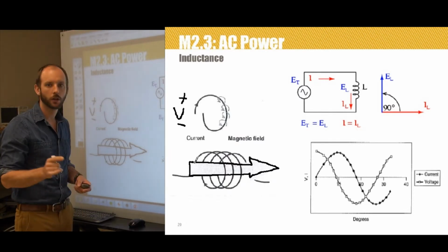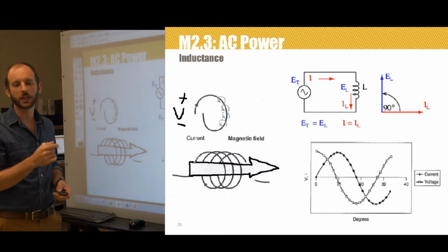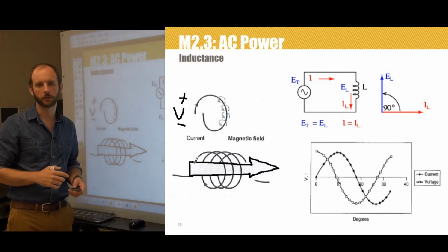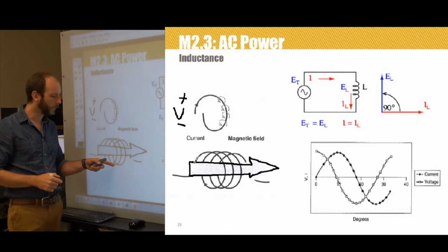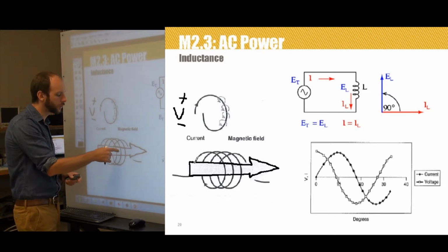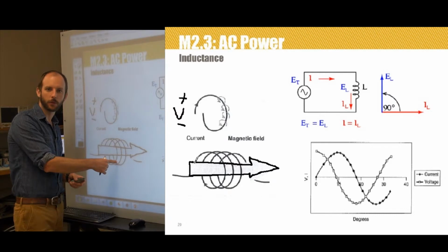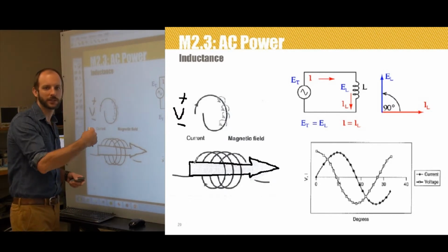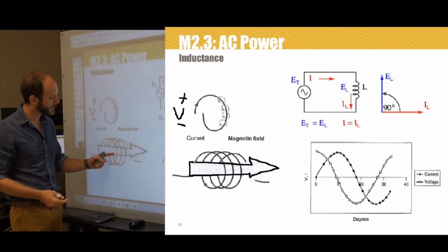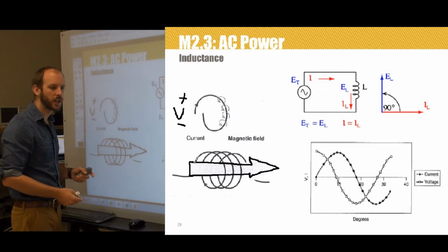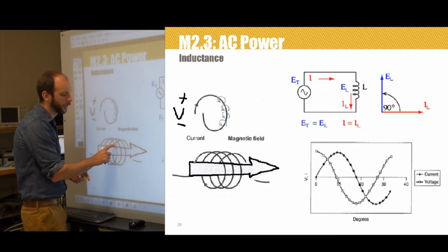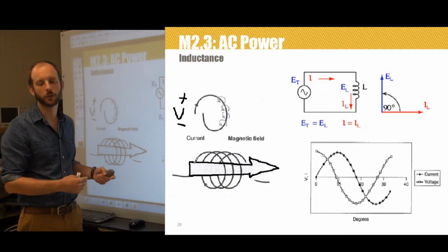And the direction of the induced current is opposite to the current that originally produced the magnetic field. Since the coil itself is a conductor, this flipping magnetic field induces a current back into the same coil, but the induced current runs in the opposite direction. So I've got one current flowing from left to right around the coil, which establishes the alternating magnetic field, but then I get a tinier current that flows from right to left and opposes the original current.